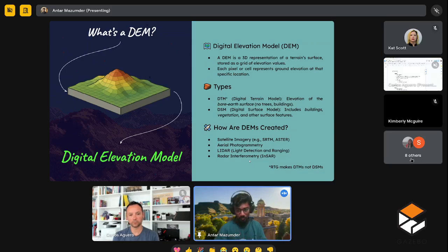And there are two types of DEMs. The first one is DTM, which I am addressing, which is the digital terrain model, which doesn't have features like vegetation or buildings and so on. And there is another version of it known as the digital surface model, or DSM. In that case, we are going to consider multi-view angles, so we have to follow methods like MASt3R-SLAM, Gaussian splat, or Facebook's VGGT, if you're interested. DEMs are usually created using satellite imagery, LiDAR or radar techniques.